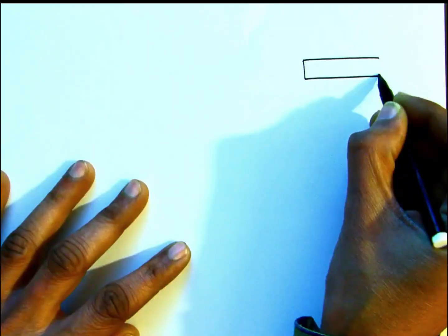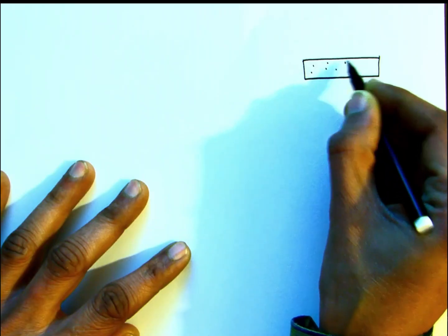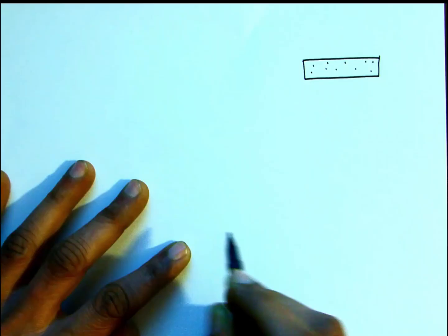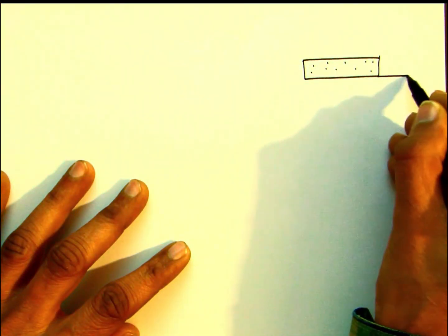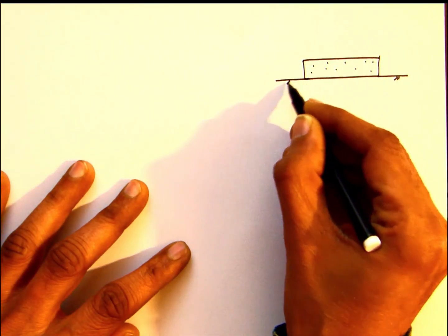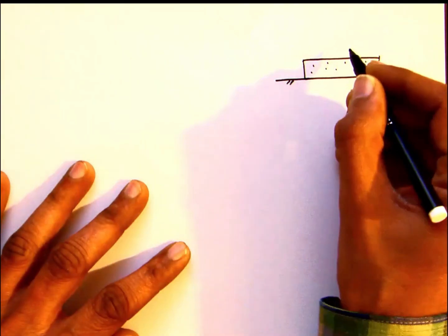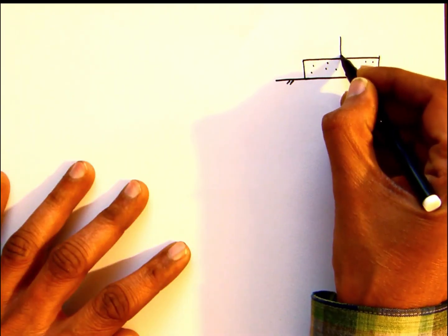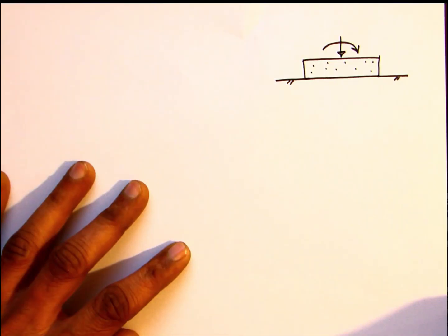The next elastic constant pertains to rotational vibrations of the block foundation, that is connected with rocking and pitching. Now under these cases the soil is under bending and hence the stress under the block foundation, which is in the vertical direction, is non-uniform in nature.